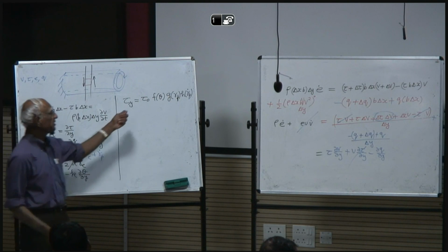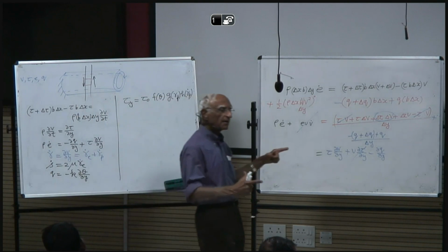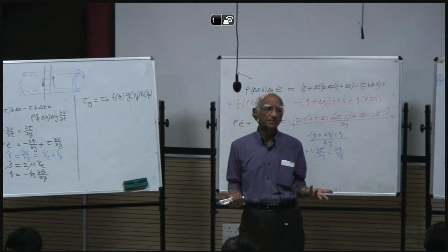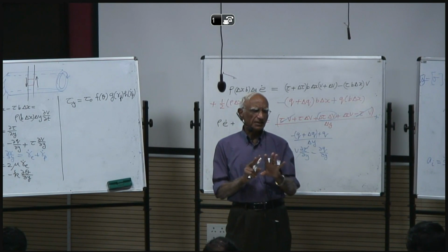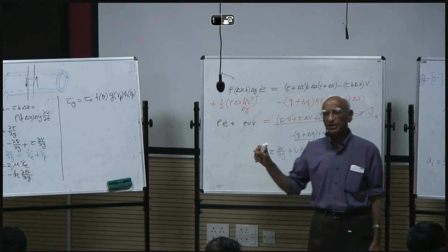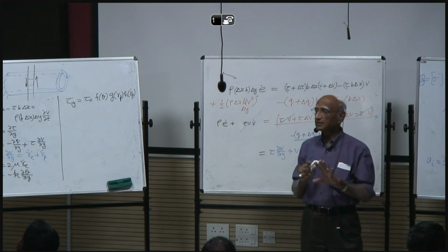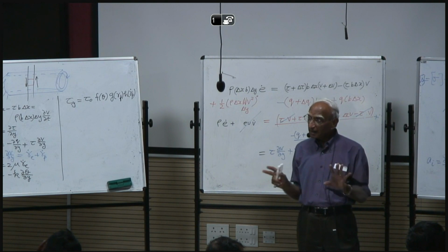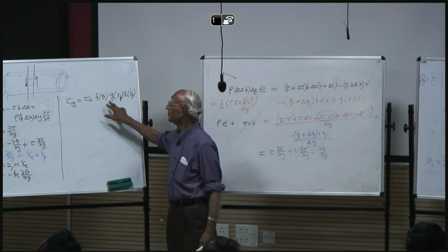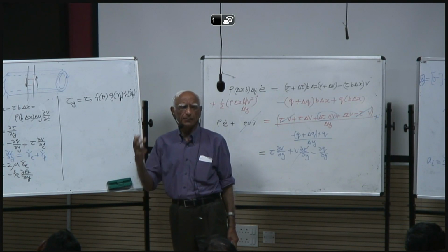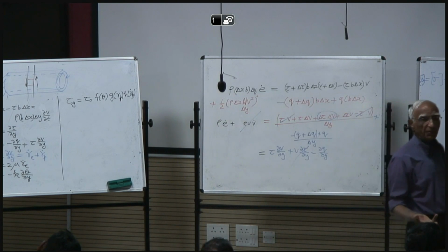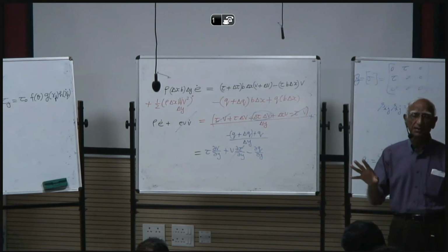So the forms of these functions determine how rapidly or how slowly the material is hardening and softening. Assuming that they are multiples of functions of temperature and strain rate is an assumption. In real life, nobody knows how the materials behave when you change the temperature, strain, and strain rate, because as soon as you deform something plastically, its temperature changes.